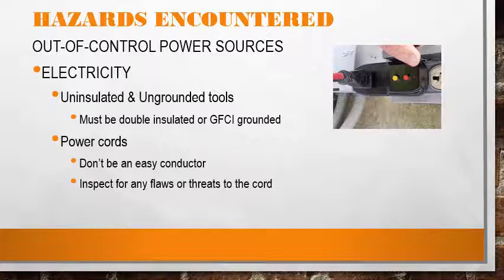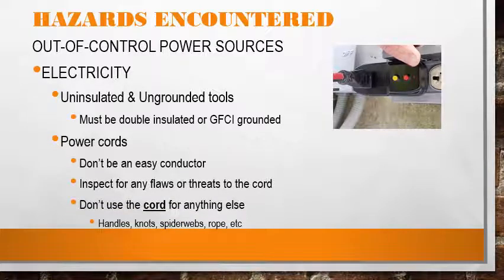Inspect your tool cord and your extension cord for any flaws. And don't use your cord for anything else. Don't use your cord as the handle to lift up your tool. Don't use the extension cord like a rope to pull your tool toward you. Be careful what kind of knots you put in your power cords. Knots can pinch and force the plug to come loose or damage the plug.